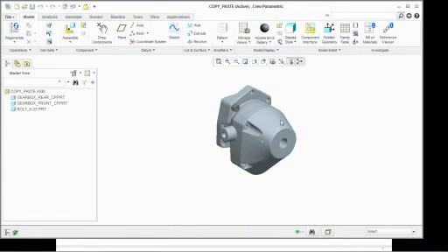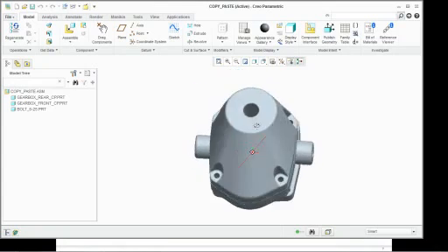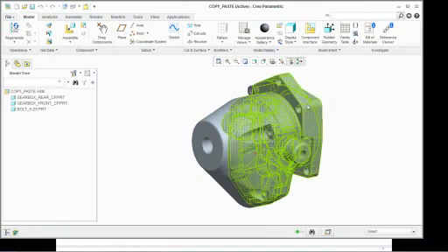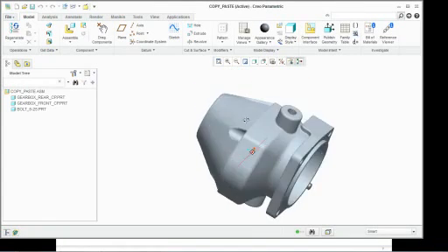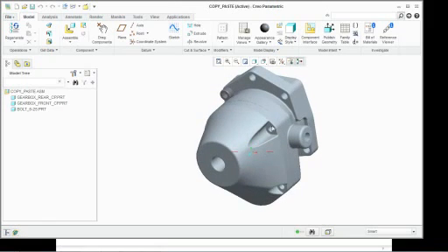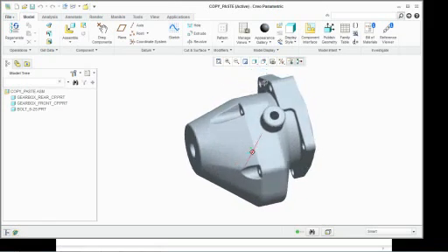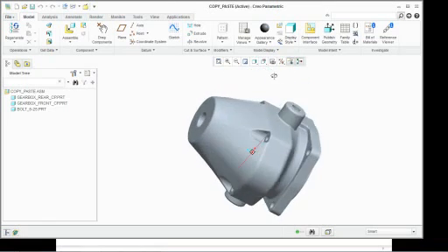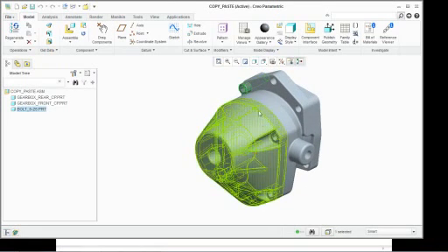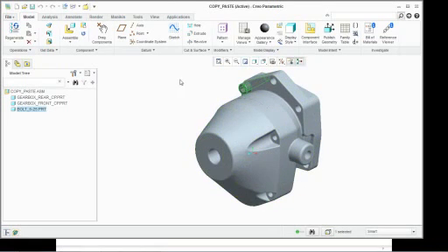One thing most people don't realize is how to place bolts. It's simple to place bolts on a large group of something if they're in a good geometric pattern. But in this case, I've got 3 bolts up here. They're not really patternable, and I've got 2 more bolts on bottom. Well, I can select this bolt, hit Control C to copy, or click here to copy, and then click paste, or hit Control V to paste.